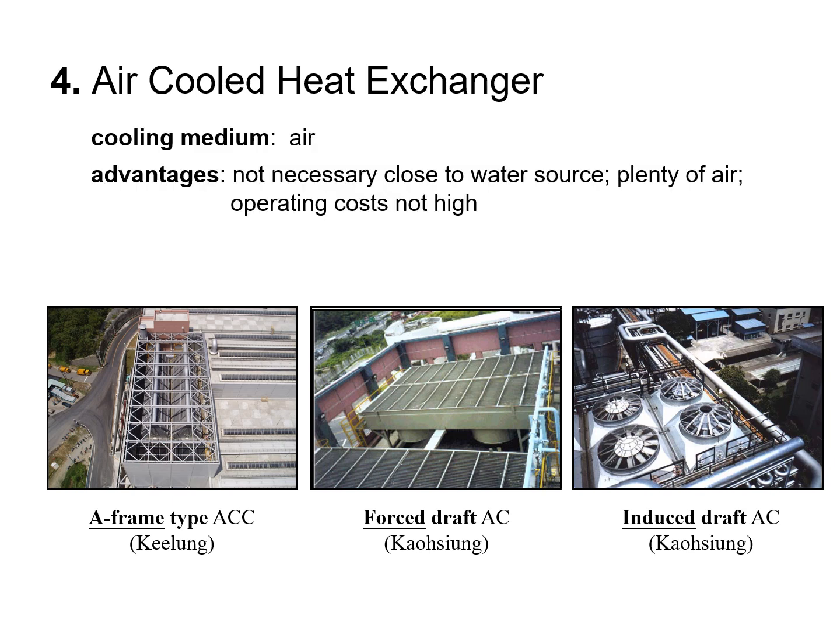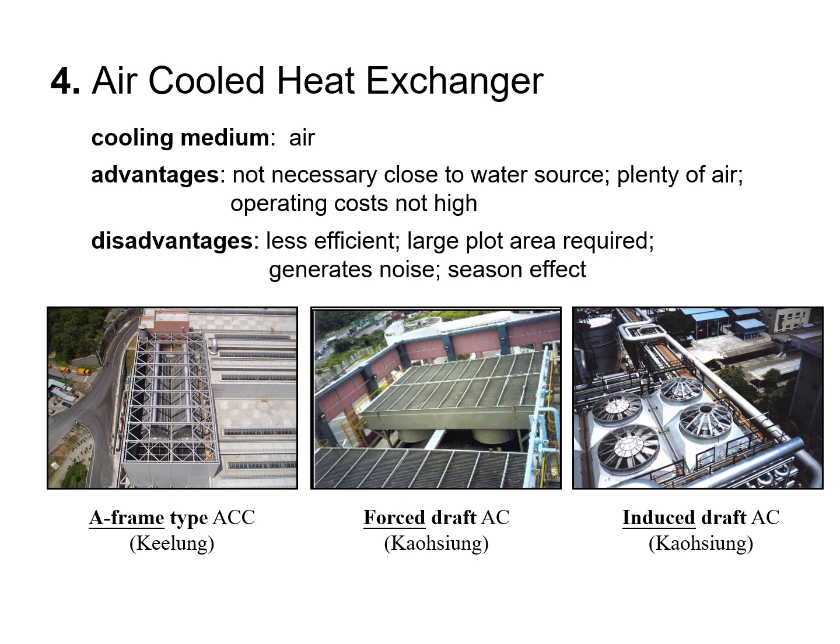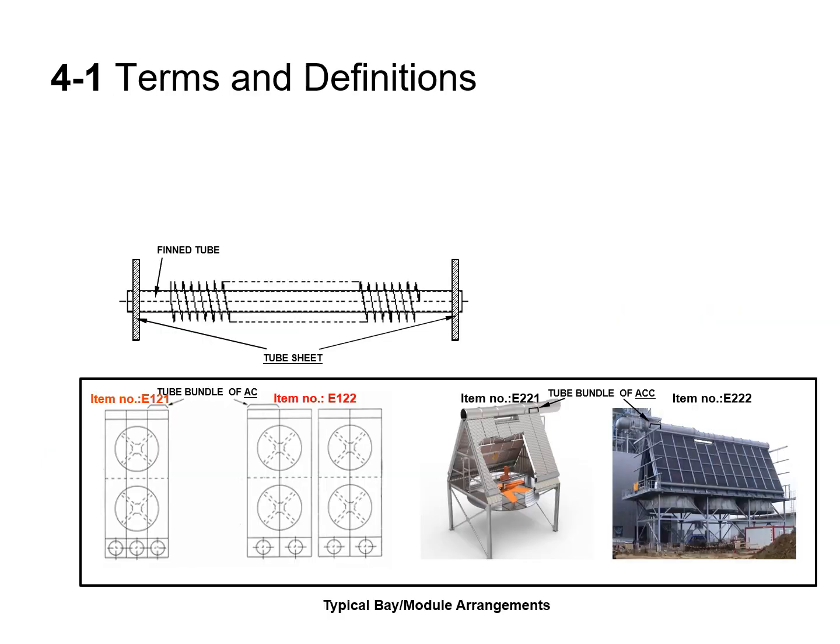These air-cooled heat exchangers are used to cool fluids with ambient air. The advantages include no need to be located near a water source, easy access to air for cooling, and lower operational costs. However, there are also disadvantages, including lower thermal efficiency, the requirement for a large installation space, potential noise generation, and a large effect on the operating performance from day-night and seasonal temperature variations. Next, let's introduce some terms and definitions related to air-cooled heat exchangers.